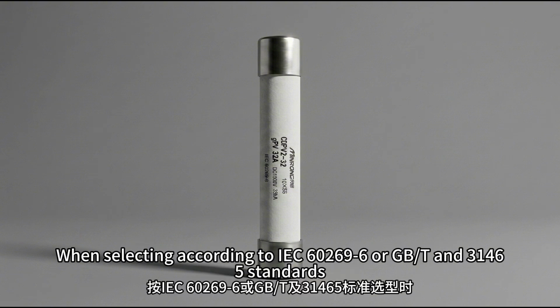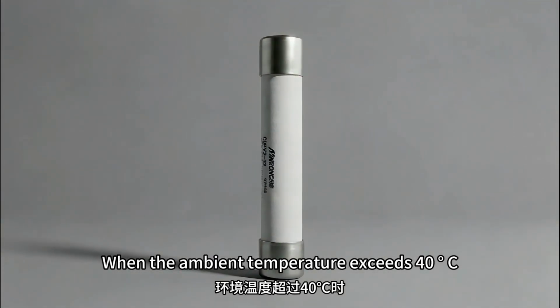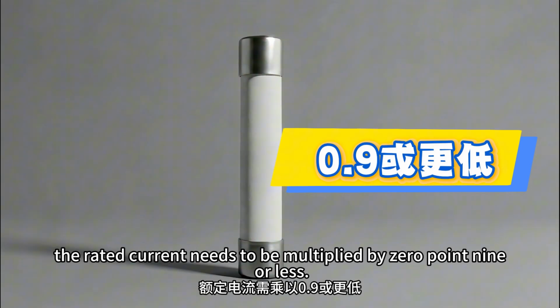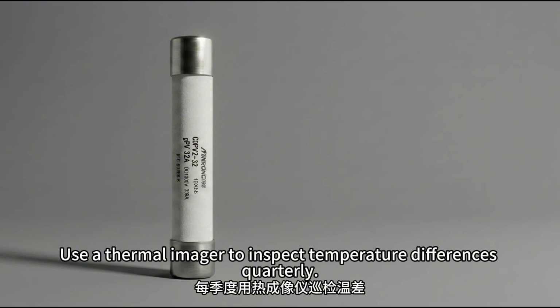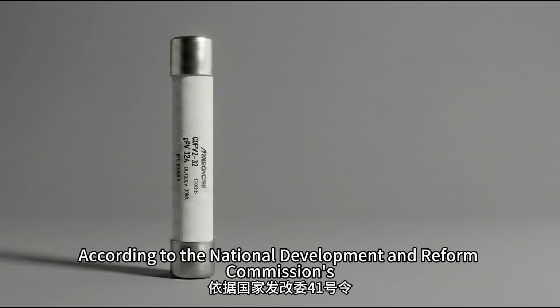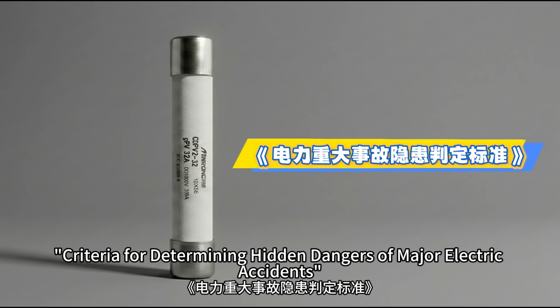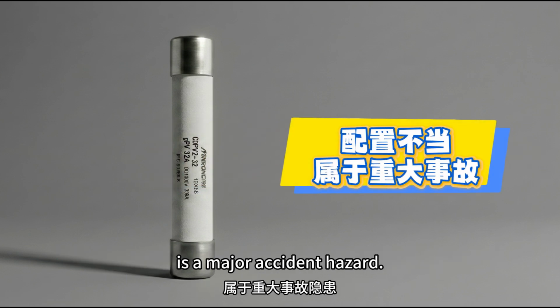When selecting according to IEC 60269-6 or GB/T 31465 standards, the temperature derating coefficient should also be noted. When the ambient temperature exceeds 40 C, the rated current needs to be multiplied by 0.9 or less. Use a thermal imager to inspect temperature differences quarterly. Exceeding 20 C is an early warning. According to the National Development and Reform Commission's criteria for determining hidden dangers of major electric accidents, improper protection configuration on the DC side is a major accident hazard.